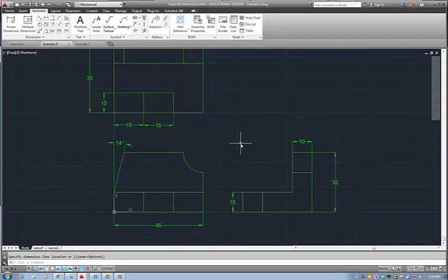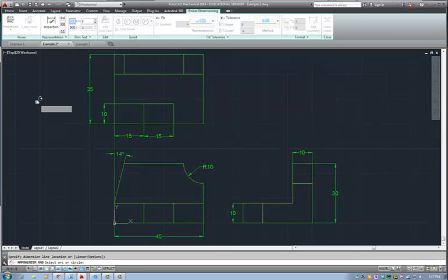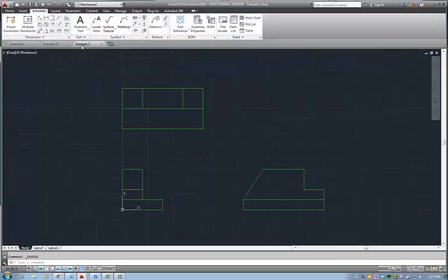So you see, it would be the best if you would be able to measure shapes where you actually see them. So if I measure the radius, wherever I see the circle, I will put R10 here, not here, where I see the line. And the same stands if you have a triangle missing, or a rectangle in this case, or a rectangle in that case. And at the end, I would like to show you example 3.